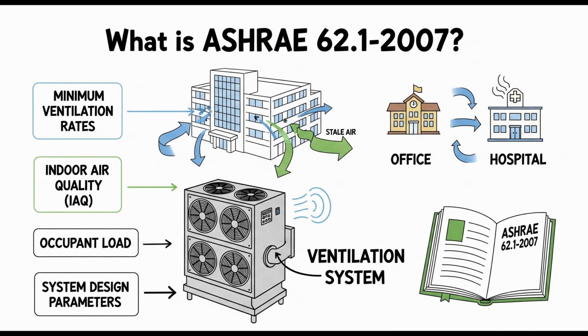Obvious things like checking and changing filters regularly, inspecting cooling coils and cleaning them if needed, checking drain pans to make sure they're clear and draining, checking fan operation, humidifiers if you have them. What about the outside parts? Yeah, inspecting the outdoor air intake louvers and screens at least every 6 months, looking for blockage from leaves or debris, making sure the bird screen is intact. Also, checking sensors used for control systems, do they need recalibration?